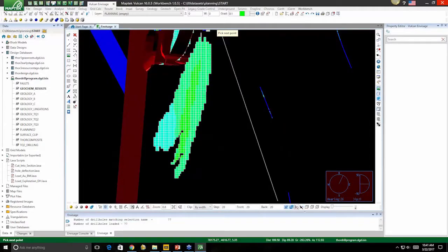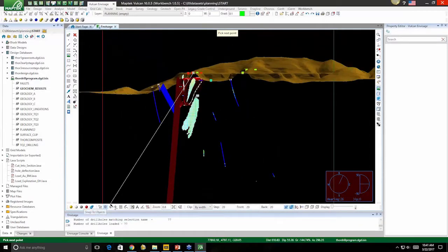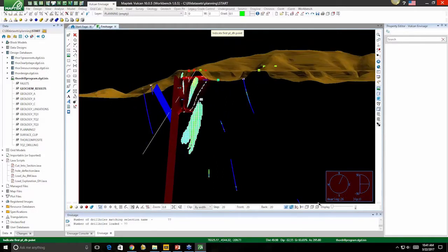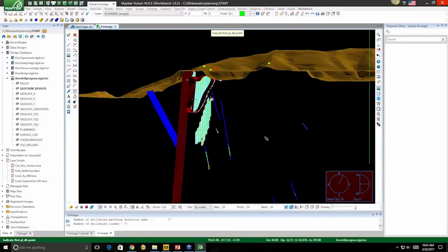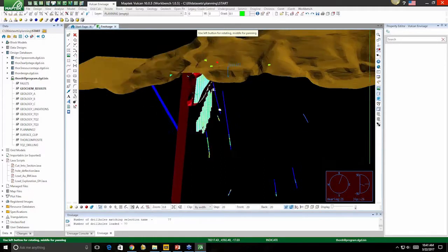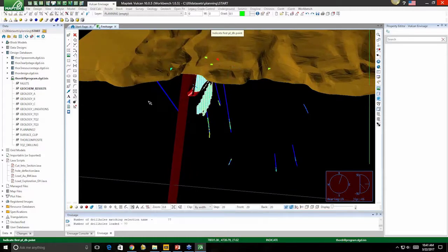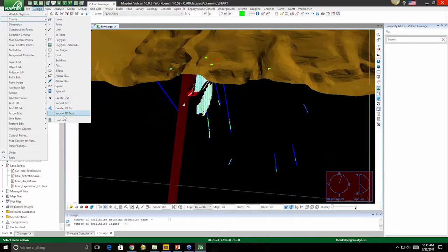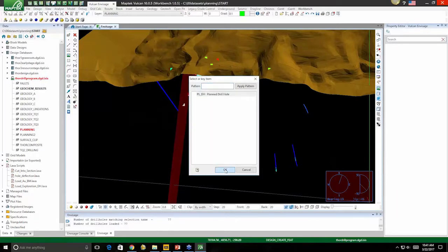Okay? I'll go back into my section. Using the N short key on the keypad, I can toggle between the different snap modes. And then I will snap right there. And then maybe I want to advance a few, and maybe I want to go ahead and use that same position there. Oops. Go back in here. Again, I can make some shortcuts as well to help with this process.